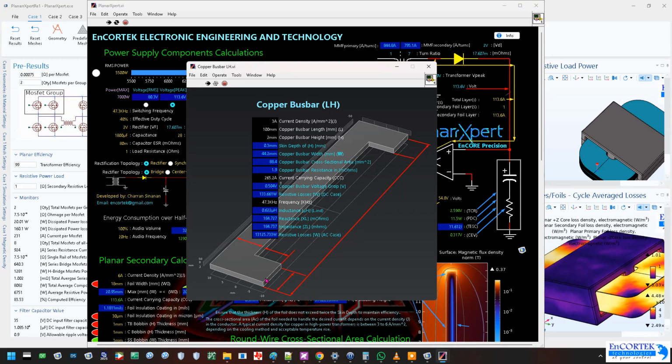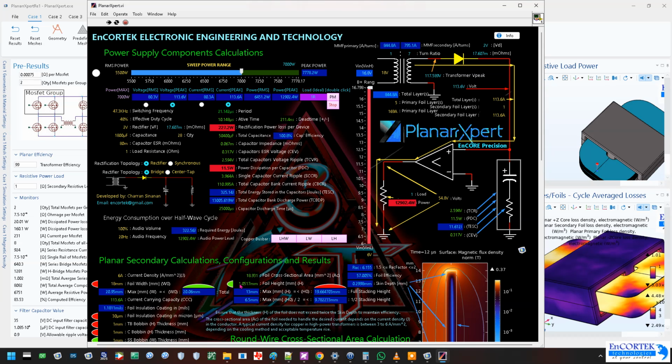You don't want to put one thick bar. The current will travel in the surface, the internal will form heat, current will be pretty much a disaster. So you know, at high frequency the current tends to travel on its surface, so you don't want to have a thick current bar, because you know that is for DC. DC is fine, but when you're doing AC, you need to run one or two of these guys itself, so you have to take that into account, right? I didn't bother to put these things here. If you're designing, you're supposed to know those things, right?